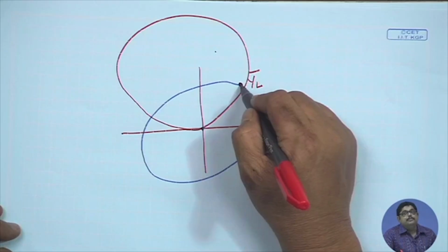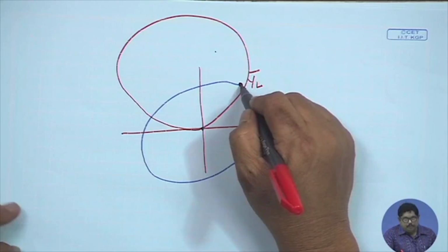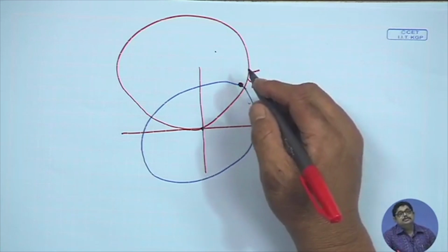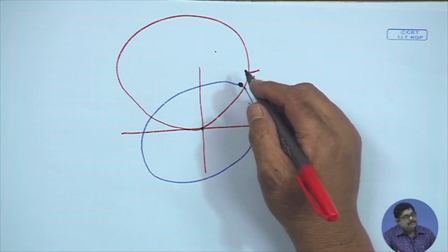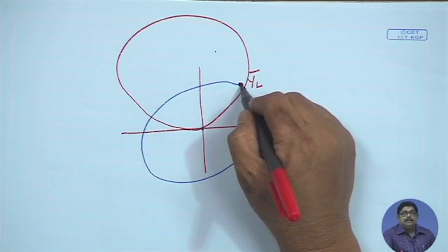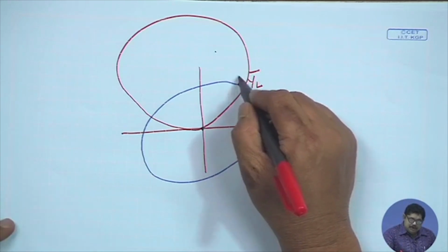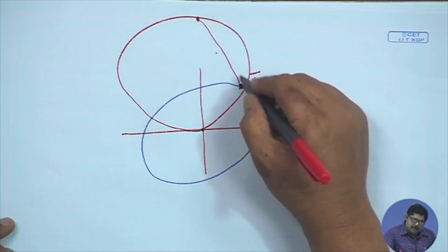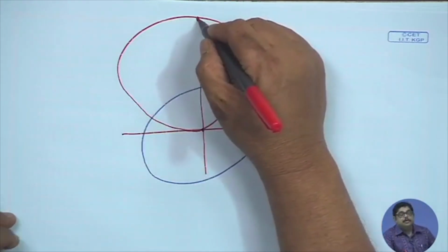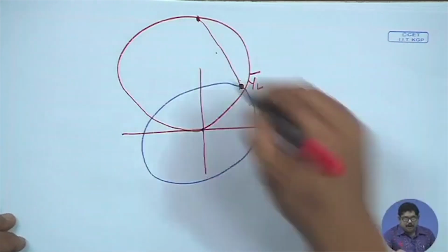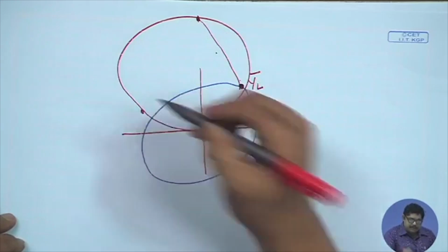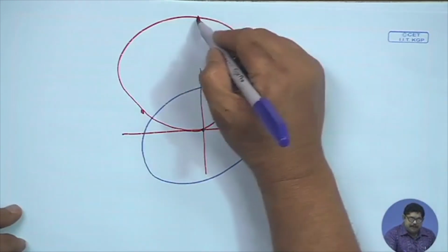So, from here you should be on the constant conductance circle, and you change to cut some point, that means you are on a constant resistance circle, but move and come to either this point, or if you proceed, you can come at some other point, take any of that.